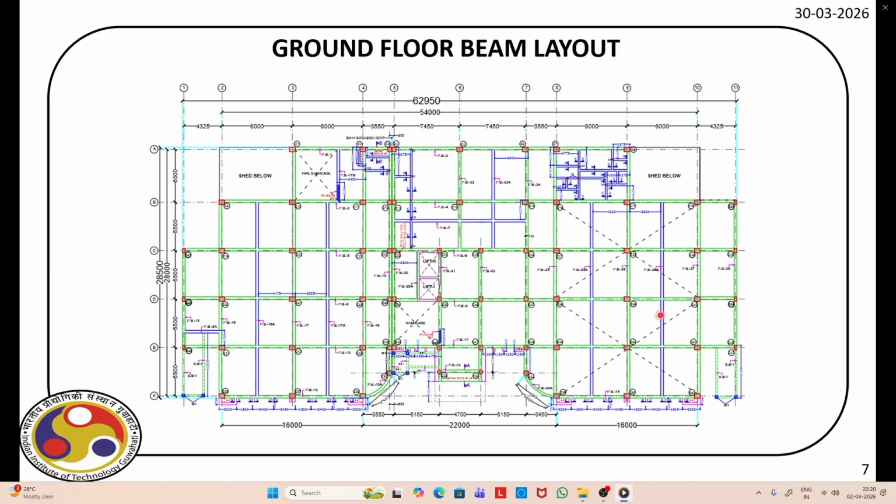Now in this part also we have green lines and blue lines. Green lines are main beams and blue lines, if you can see, are secondary beams. Because this is a demonstration session, we will not prepare the exact blue lines. For example, you can see this grid just right of grid 7. There are a lot of blue lines there. We will approximate those with two secondary blue lines. As you progress, you will see that. However, you can prepare a very detailed model as per the dimensions if you follow the steps we are going to adopt in this modeling.